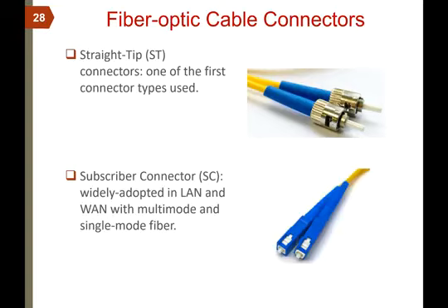You need to terminate, of course, fiber optic cables, like coaxial cables, like Ethernet cables. So how do you terminate them? You use different kinds of connectors or terminators. So we have the straight tip. You don't need to remember these, just ST, we call them ST connectors.